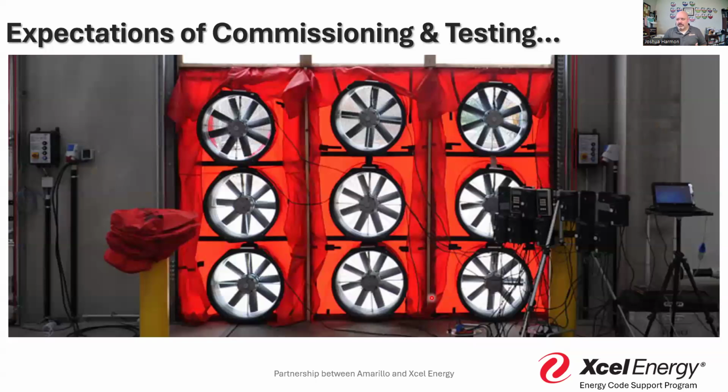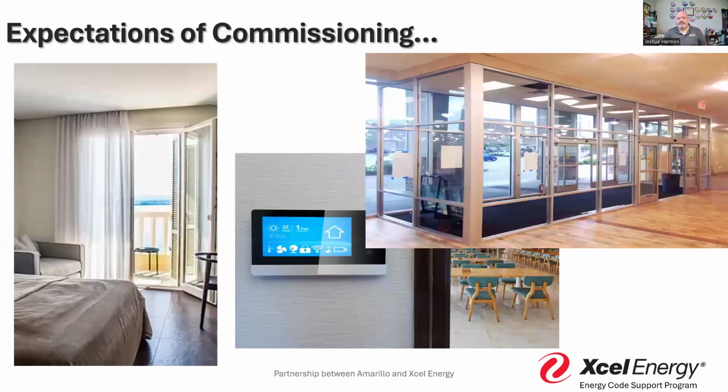Again, this is a little bit larger example, maybe for a loading dock area that we might see in a commercial project. And so just to show that we can see them at different sizes, different situations. Again, if we're part of a hotel or something, ultimately what we're doing is we're making sure that the system, not only the ducts, but also some of the controls, right? The controls that would tell the equipment to shut off when I've left the balcony door open for 3 days, or if this balcony isn't closed, then I don't want this air handling system operational, right? And so I want to make sure the controls are working right and we have the proper isolation.